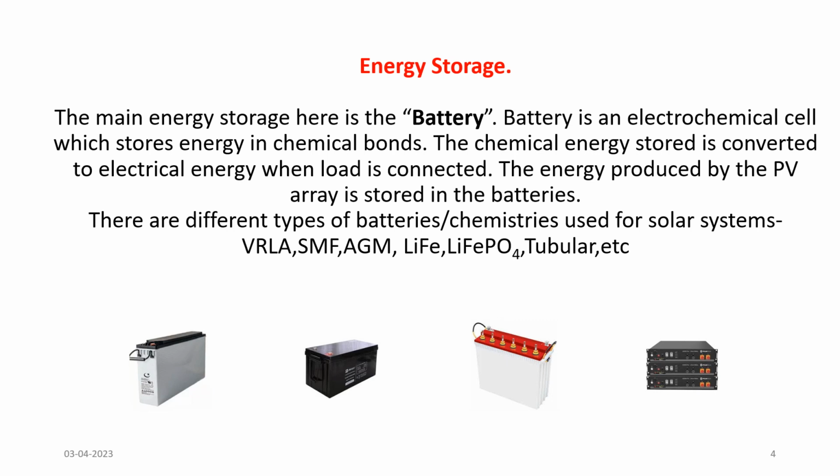And this lithium ion is different from others, because most of them have their depth of discharge between 90% and 95%. That is, we can deplete them. That's the advantage they have over other types of battery, because other types of battery like the SMF, the VRLA, the tubular batteries, their depth of discharge, that is the DOD, most of them ranges between 40. Even if hardly will you have 40, most of them like 50%.